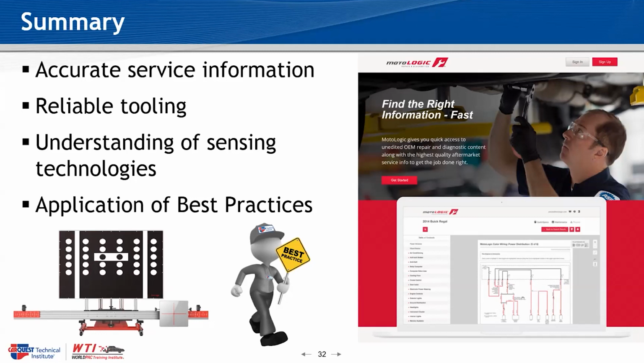The tire pressure is a huge one, like Randy said. I think the pictures are in another class, aren't they, Randy, of the laser on the emblem? They are. That's correct. It's in the 4-hour version of this class. And it's a massive change just airing a tire up directly at the vehicle. I think Jim brought up some better math, knowing that at a certain distance farther away, the amount that it's off is significant. And we talked about that with just thrust angle.